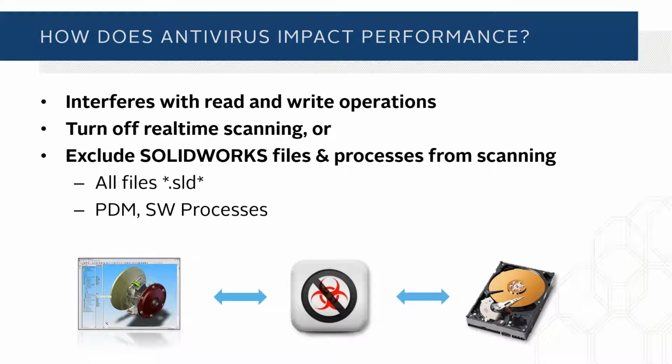With real-time scanning turned on, every one of those 6,000 documents is going to be intercepted by the antivirus software every time you open or save it, which can cause SolidWorks to wait a long time. Relatively speaking, the operation may happen, or it can just give up and crash.